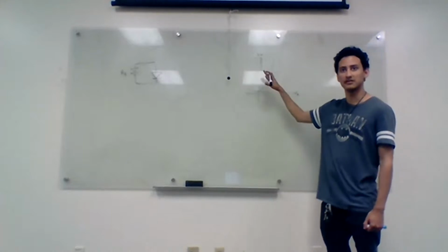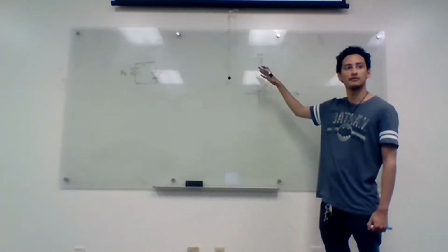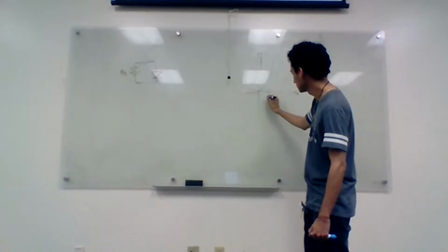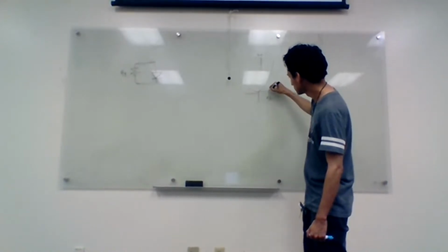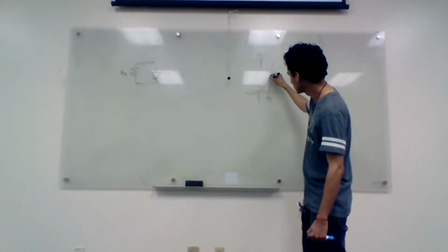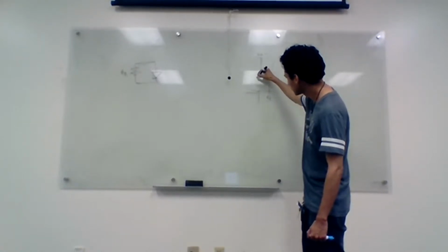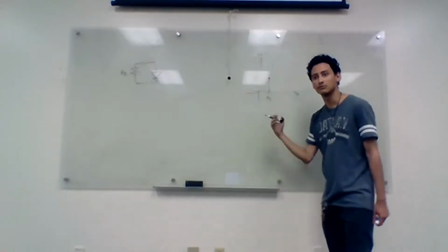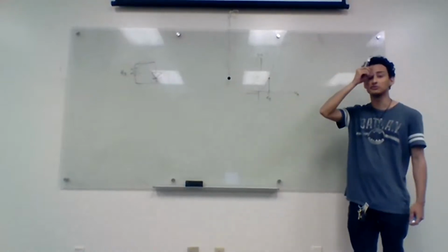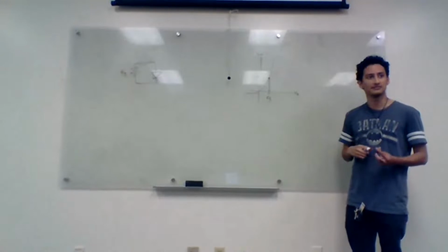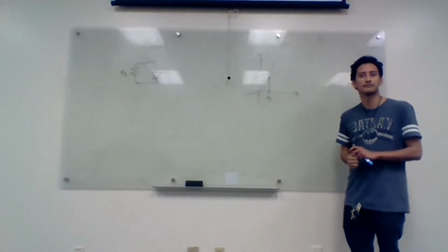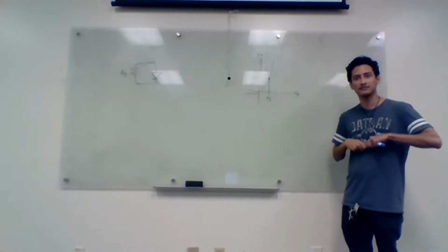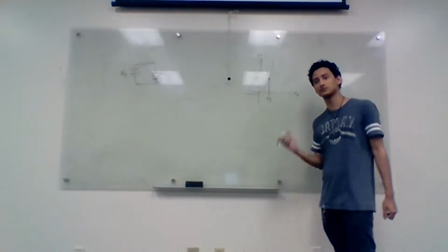We either set a voltage or we set a current, and that is where we're going to operate. You know, I'll write something for BJTs, you'll see IDQ a lot. ID quiescent, and that's your operating point. And then the small signal stuff that he adds on top of it is the derivative of this.